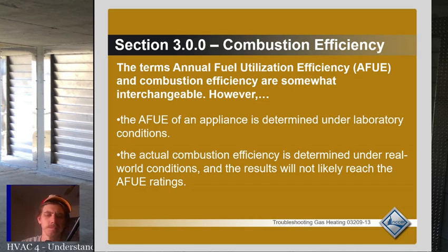So I don't think we've discussed it in this class yet, but you can use a heat rise method to determine how many CFM you're putting out. I think I talked to you guys about this before briefly too, but when you do it on a gas furnace, you need to know the BTUs you're outputting when you're doing something like that.